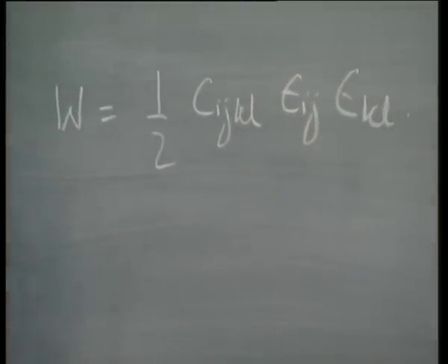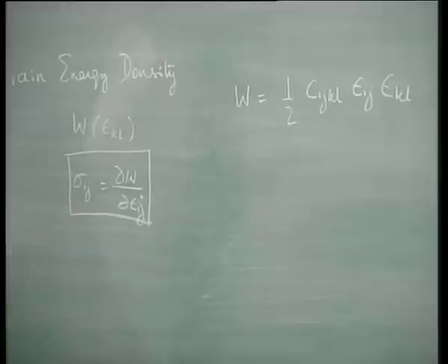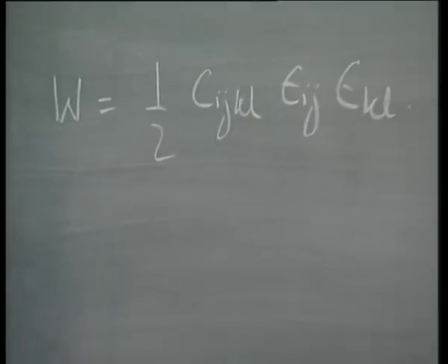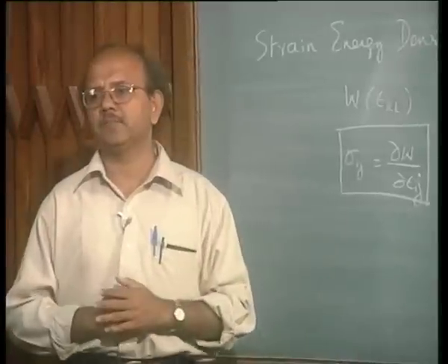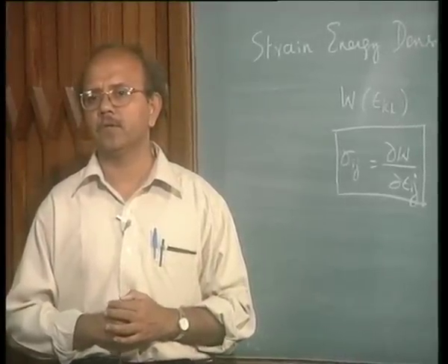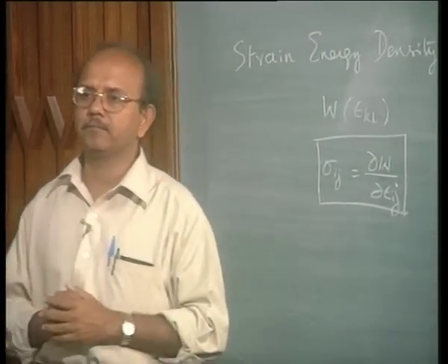The definition of strain energy density function, say for example definition of this function is quite involved. Okay, there are a lot of things that you have to satisfy, but I am not going into the details of how I got this, because that is a separate course altogether. But nevertheless, satisfying some very fundamental criteria which are based on thermodynamics and so on, it is possible to write down functions for a class of material. For example, this is the function for a linear elastic material. Okay. Similar functions can be written down, for example, for an elastomer or rubber and so on.